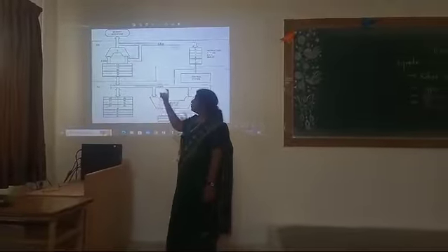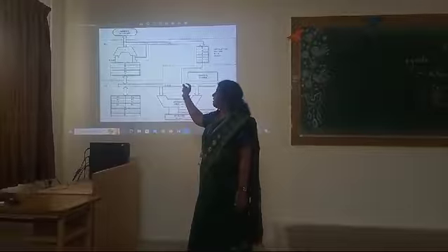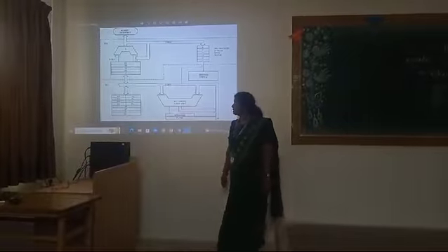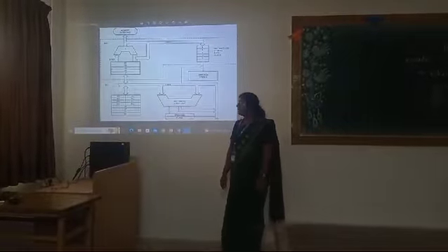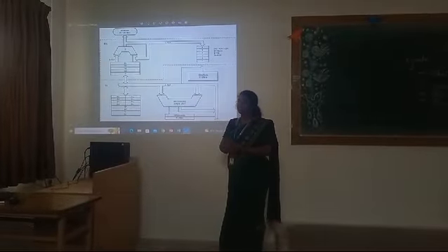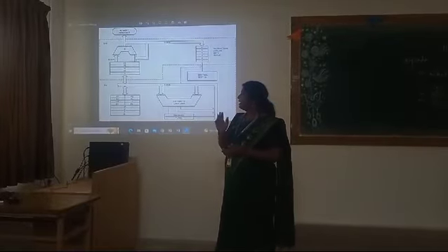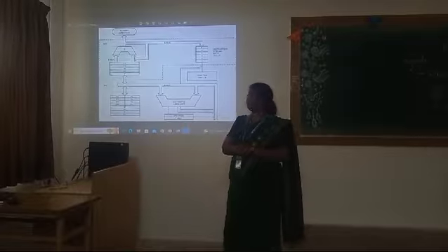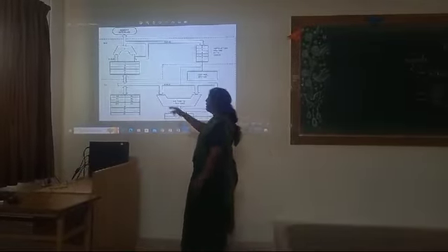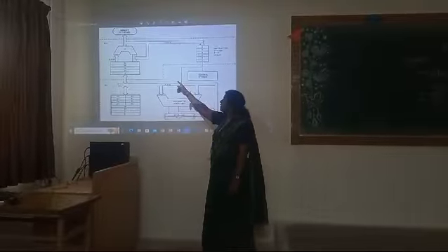They are used to store the address locations. ES is the extra segment, CS is the code segment, SS is the stack segment, and DS is the data segment, right? So the program related functions will be stored in the code segment, and stack related functions will be stored in the stack segment, and the data segment and extra segment are used for data storage purposes, with the related addresses, okay? And IP is the instruction pointer, and the summing unit is there, right?